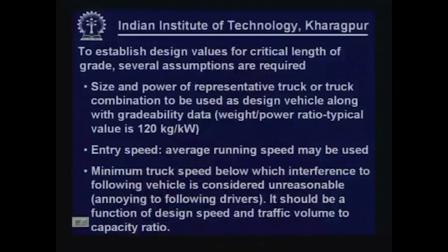Now, to establish design values for critical length of grade, several assumptions are required. Number 1, size and power of representative truck or truck combination to be used as design vehicles, along with gradability data, that is weight power ratio.